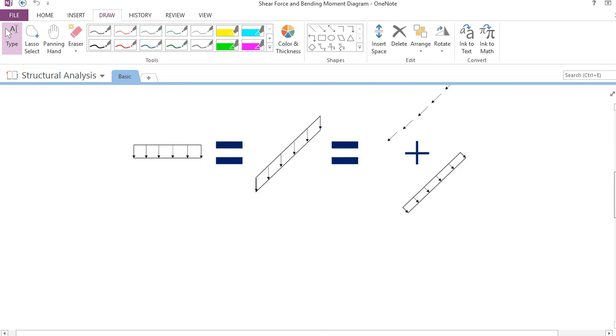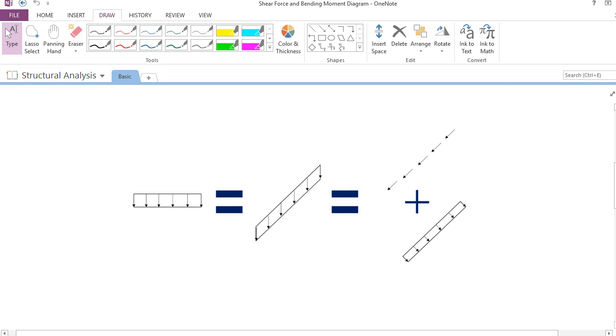What I mean is that, for example, for the first distributed load, you need to transform it to this kind of format. You need to transform this from this. Why? Because when we draw the shear force diagram, we need to do the integration of the loadings. The loadings here refer to the loading along the slope. After you do this transformation, you need to decompose it to this direction. You need to find out the loading here in order to draw the shear force diagram.